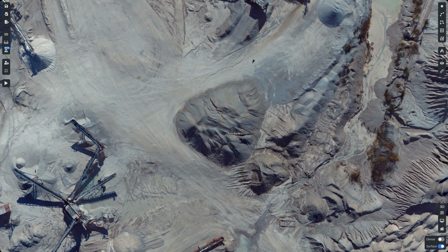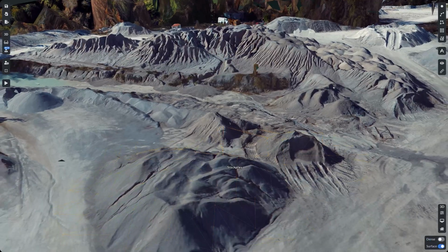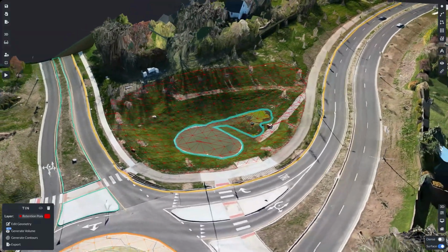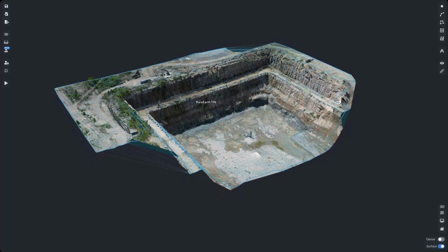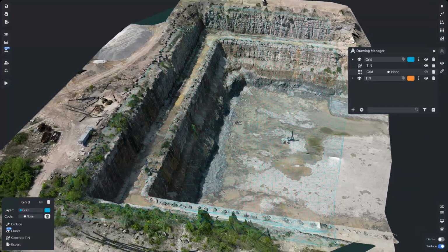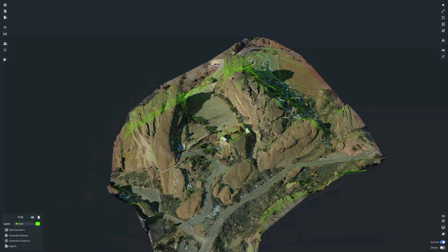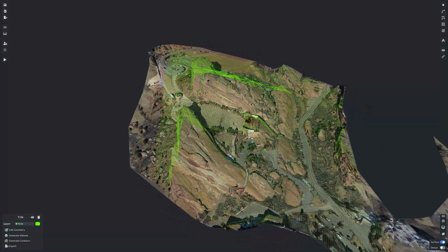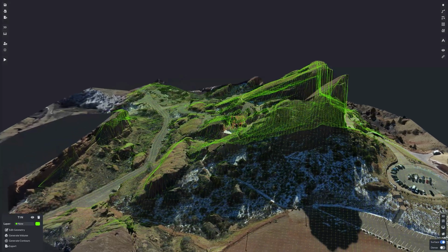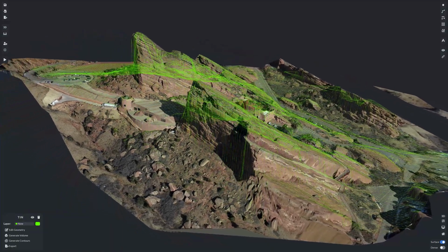TIN stands for Triangulated Irregular Network. A TIN is a type of spatial data structure used to represent continuous surfaces, such as terrain or elevation data, as a collection of interconnected triangles. These sample points typically represent elevation measurements taken at specific locations. Unlike regular grids or raster data, or even spaced contour lines like vector data, TINs can handle irregularly spaced sample points. This makes TINs suitable for representing terrain with varying levels of detail, including areas where elevation data may be sparse or unevenly distributed.